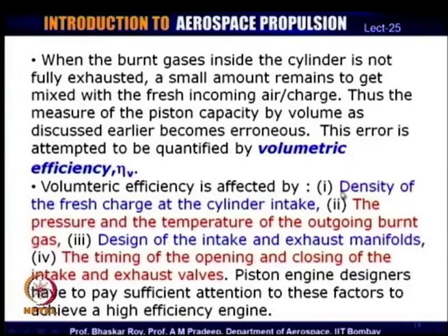What happens is the density of the fresh charge affects the volumetric efficiency, and we have seen in aircraft engines we need to increase this density through the process of supercharging, and then the pressure and the temperature of the atmosphere, the temperature of the outgoing burned gas which has remained or the residual amount, and then of course, how quickly or how efficiently the intake and the exhaust valves or manifolds, as they are often called, open and close.